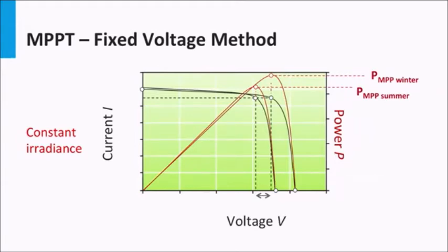This is under the assumption that the higher MPP voltages are expected during winter and lower MPP voltages are expected in the summer for the same level of irradiance. Of course, this method is not very accurate, and accuracy is increased if such an idea is implemented in a place with minimal irradiance fluctuations on a particular day.